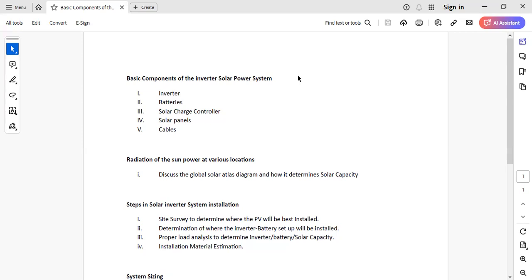So if you want to achieve high current, low voltage, you could easily parallel those cells. And if you want to achieve a higher voltage, you could just series those cells, depending on what you want. But one thing I want Hela to know is that if you have a larger ampere hour at a lower voltage, it actually gives a very good backup, because the ampere hour has increased.